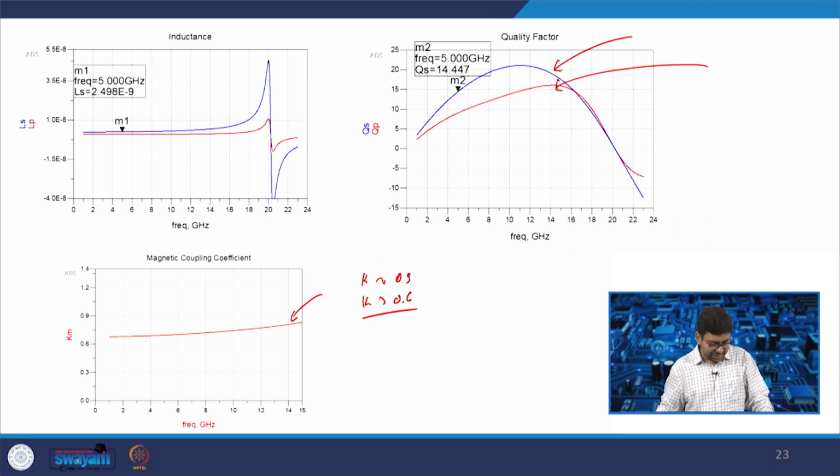Never place anything close beside the spiral inductor, or use a guard ring around the inductor, in order to reduce the noise coming in. We need to avoid extra metal filling in the inductor area, and we should maximize the symmetry in order to increase the Q. If there are more layers, there is a possibility that due to the vias your resistance will increase. So when we use multiple stacks of the inductor to improve the effective inductance, we should be careful, as the quality factor will reduce.